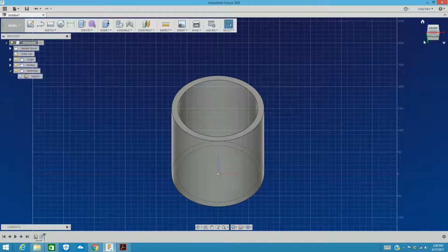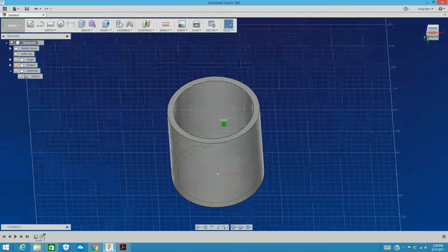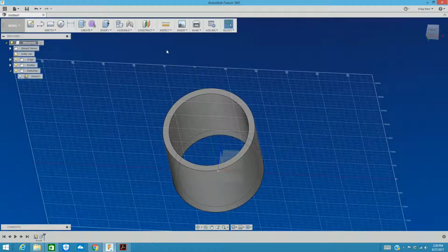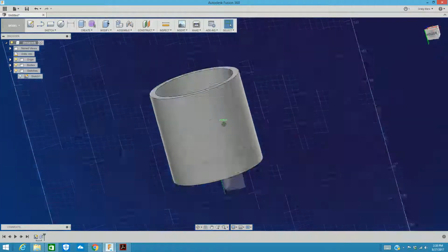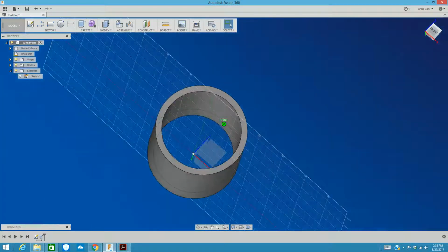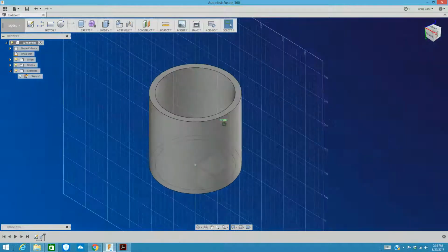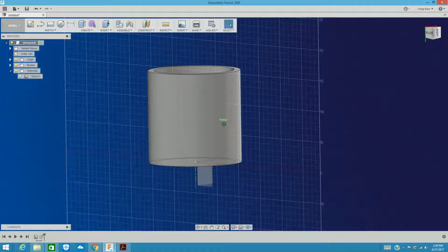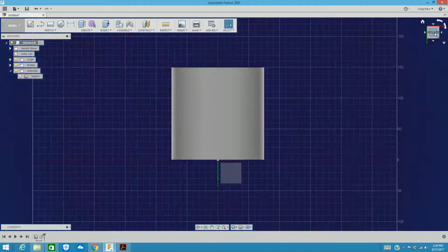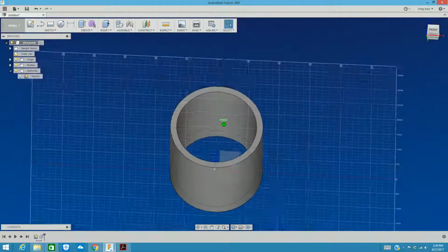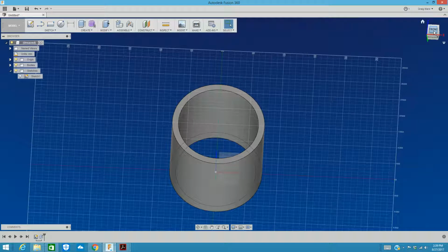There's a couple different ways that we can do this. But right now, one of the cool features I'm going to do is introduce something else under the construct feature. If you remember, I talked that we need to have two different sketches. We need a sketch that represents the shape that I want to sweep, and then the path that I want that sweep to take place. So the path isn't that hard. It can be in any plane in theory because my coffee mug as it stands now is completely symmetrical.